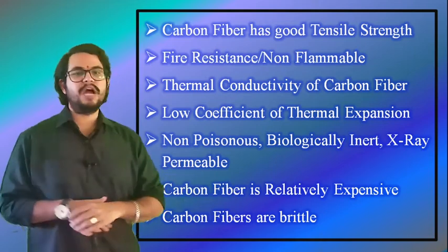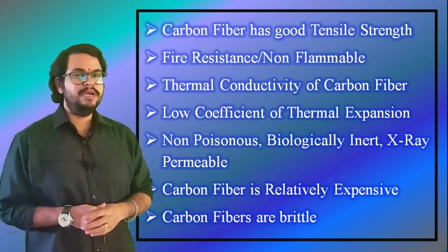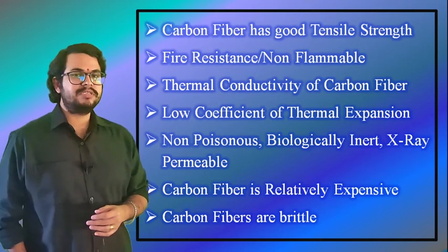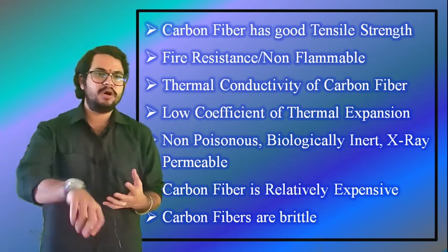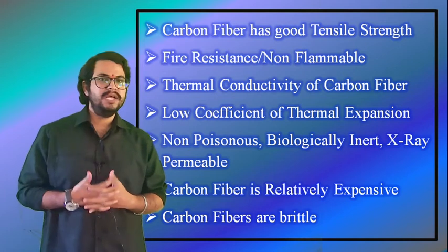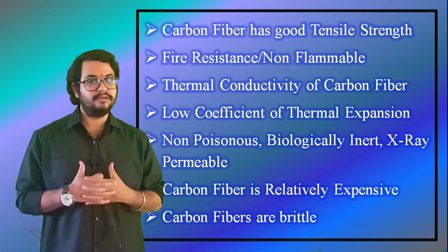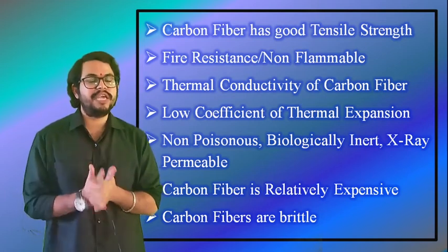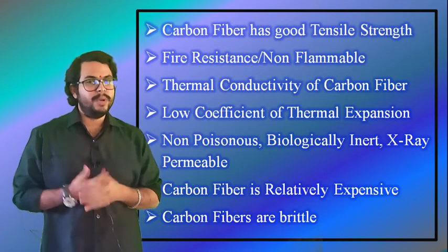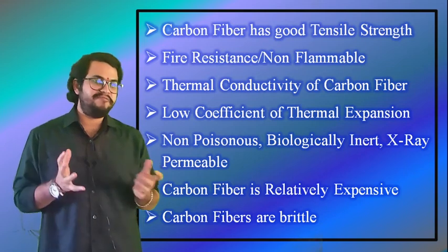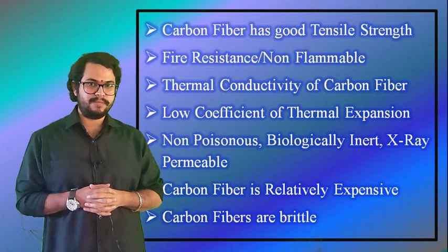The last one: carbon fibers are brittle. The layers in the fibers are formed by strong covalent bonds. The sheet-like aggregations readily allow the propagation of cracks. When the fibers bend, they fail at very low strain.